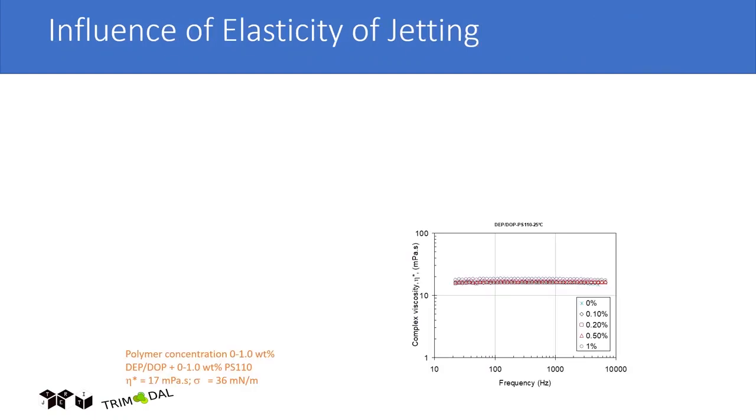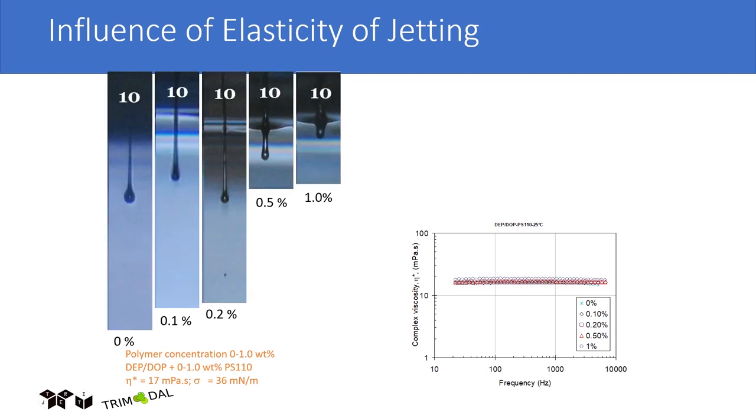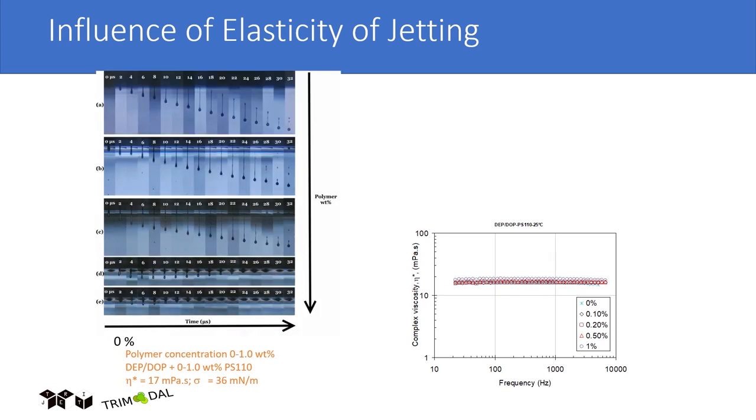Elasticity. So here's again the component analysis. You have the 5 inks I have developed, almost identical, right? Let me jet it out. Even if you look at just the viscosity of all 5 inks, I have made them exactly the same. Surface tension is the same, everything is the same. But the jetting is completely different, right? That would be your batch-to-batch variation. That could be your blend variation, everything. How would you differentiate? Again, this is what this snapshot looks like.